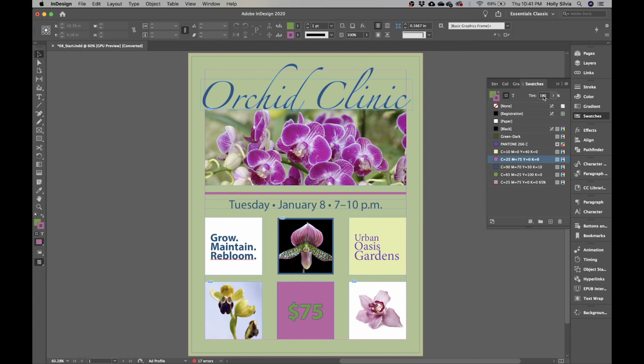The reason you might want to do that is you're going to be using the solid normal color a lot, but there are also assets that you want to color, so you're going to be using the same tint of that color as well. You're going to be using that over and over. It's quicker to just make a new tint swatch, so that way you don't have to go, okay, select, change the color, change the tint.